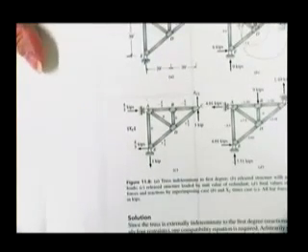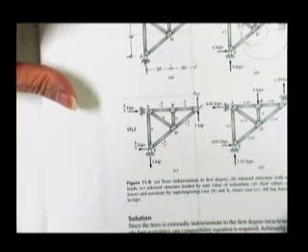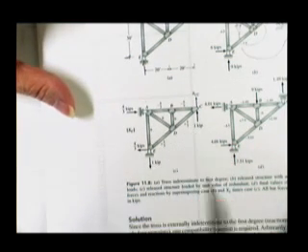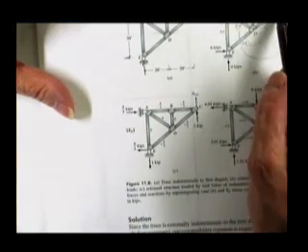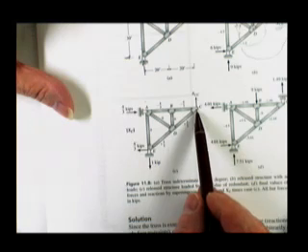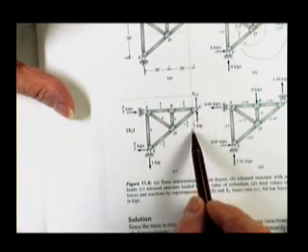Next thing you do is you take your released structure, your primary structure, and you put a unit load at the point in the direction that you would like to find any kind of deflections. Real deflections due to real loads, possibly deflections due to unit loads. You only get one choice. He decided that he thinks that this joint moves up. So he put that this reaction is up, and that this thing moves up, and that this moves up. Once he did that, he's stuck.